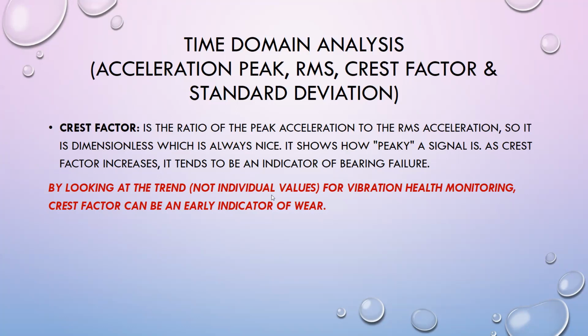This behavior is very important. For example, you have 2 or 3 different signals for a specific machine in different periods of time. If you compare the crest factor, you can monitor the vibration and the health of your structure and the components.